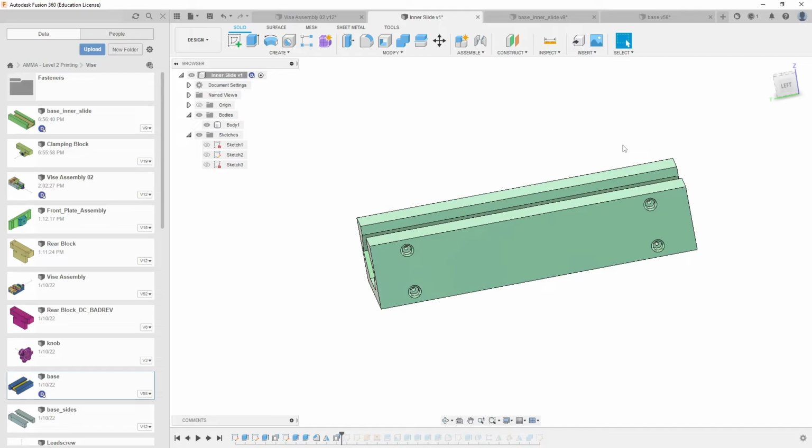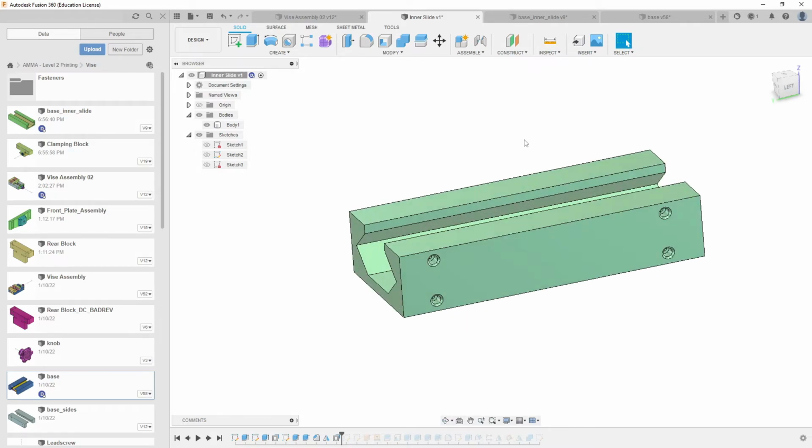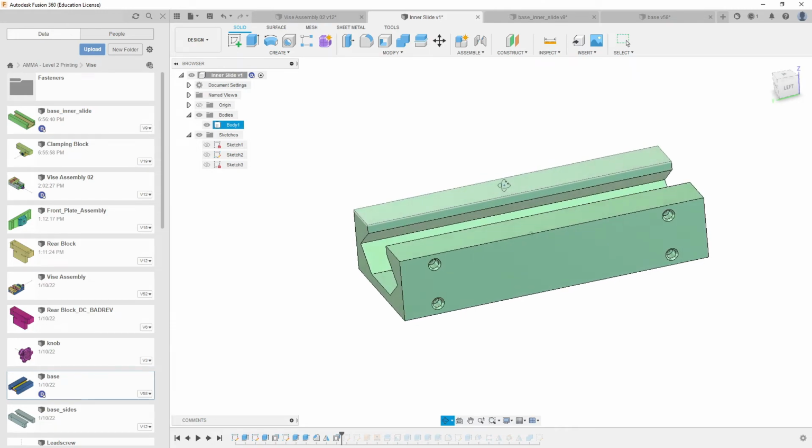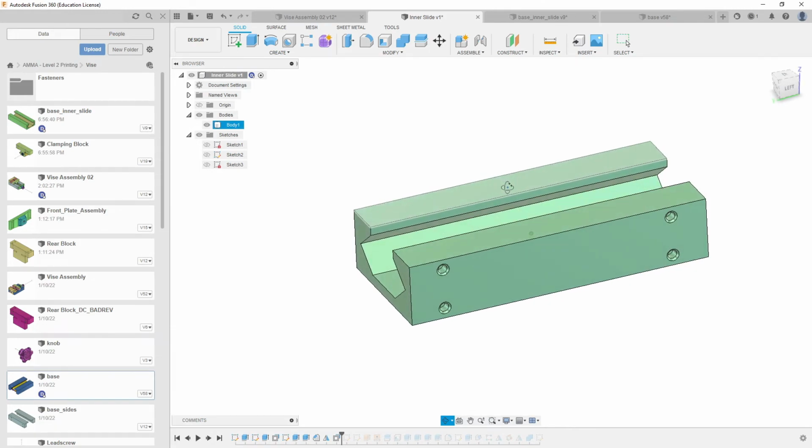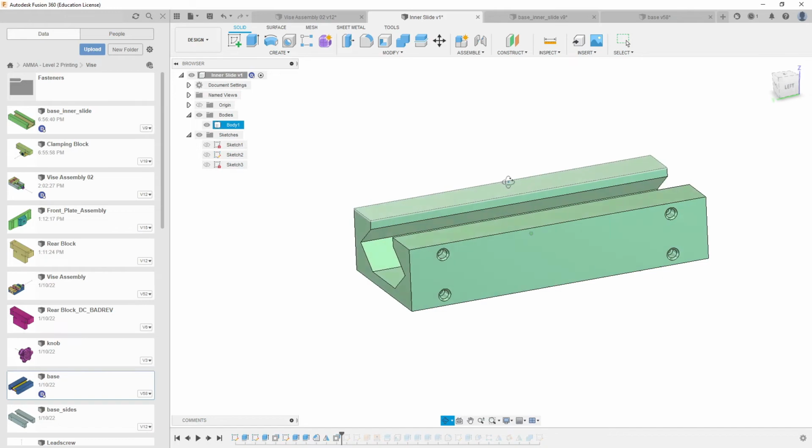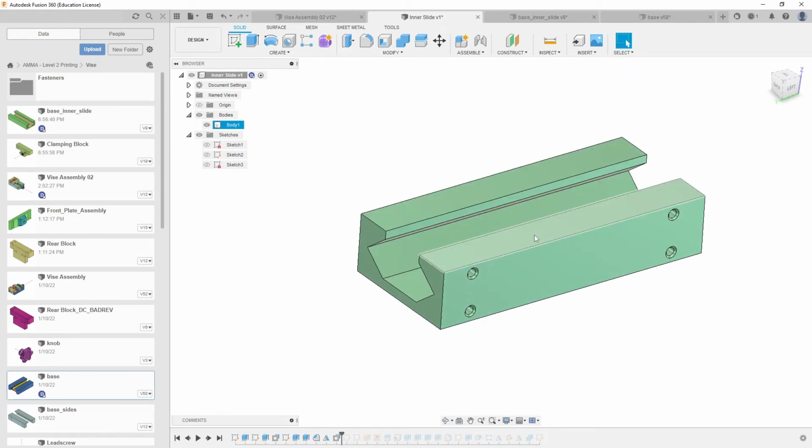That should be good. If you feel a little bit nervous about that, go ahead and make it 2, because having a gap under there is not going to be a big deal. Now, also as far as fit goes, it might be necessary, possibly, to shave off a little bit off the top. Just maybe a couple, 0.2 of a millimeter or so.